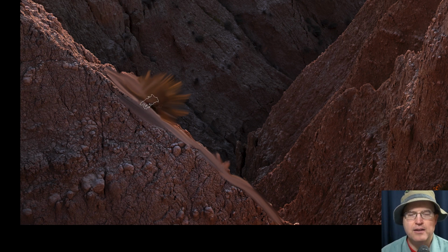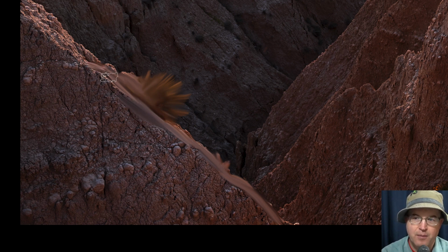Now here's another thing that's happening with this brush and how it's behaving. It is drawing information from all layers, but I already have this whole area filled in now, so it's only going to effectively draw from this layer that I'm on because it is already fully opaque. So it's going to be just smudging around the stuff from this layer. It's when I bring stuff from outside, that's where it's going to be influenced by what's going on out there on the layer beneath it, the actual image layer.